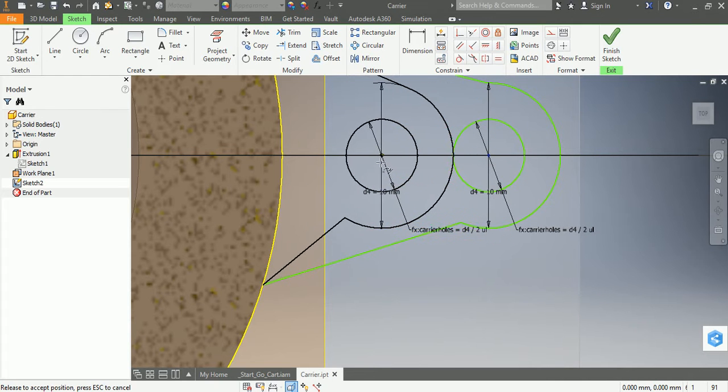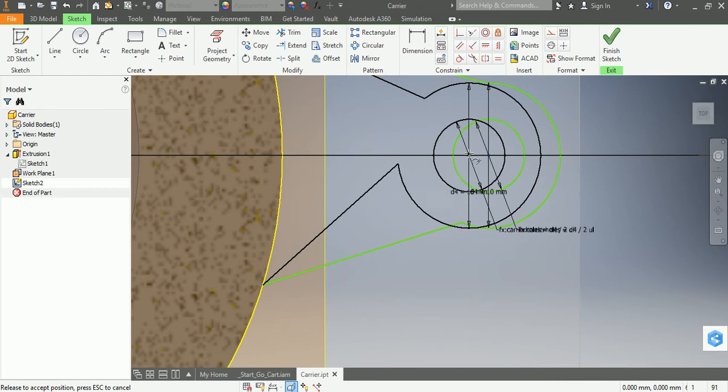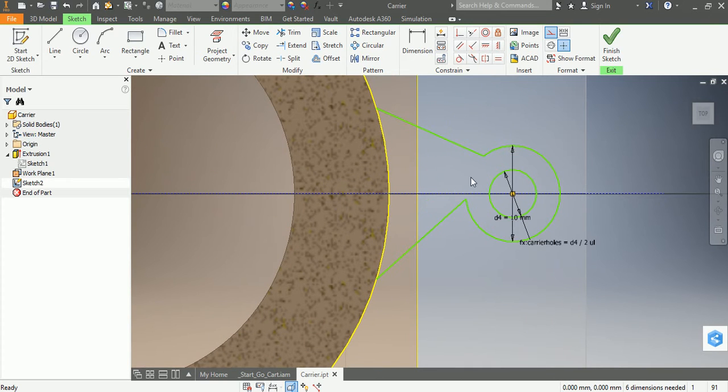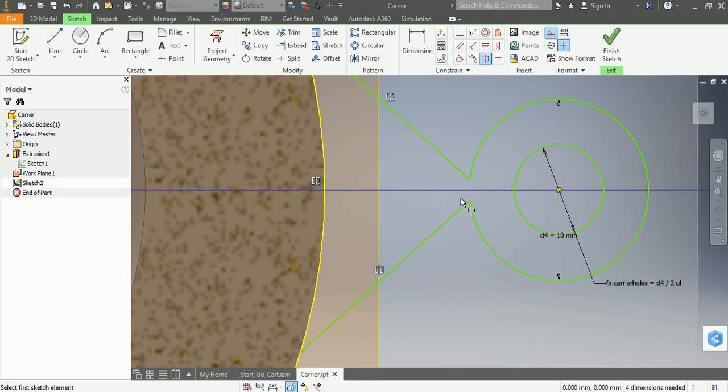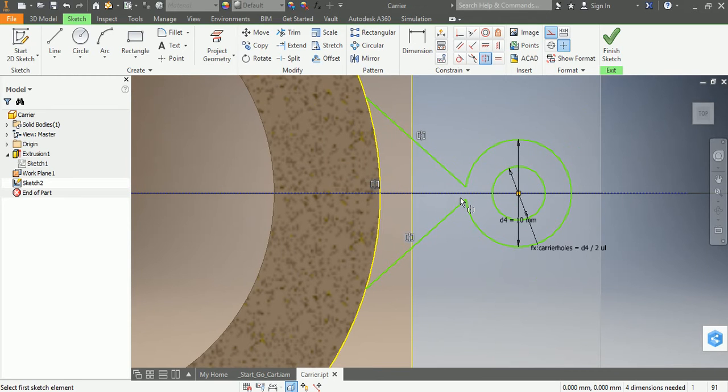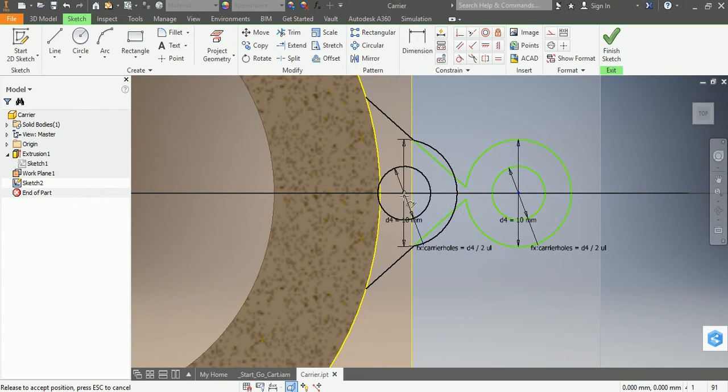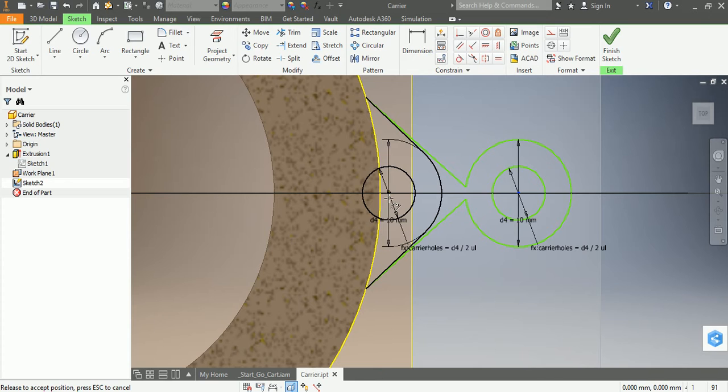Okay. Still looks kind of messed up. And if you notice, the lines are not yet symmetric. So we'll do that now. We'll set these two symmetric about this one. And now you can see it already looks really messed up. Press escape to exit the symmetry, and you'll see it's something like this.